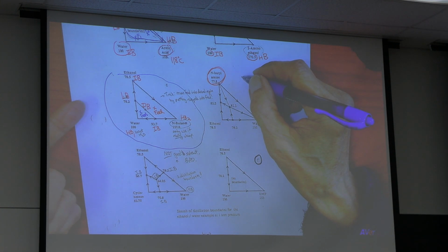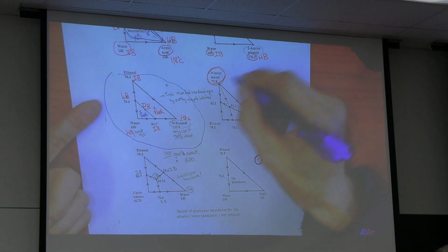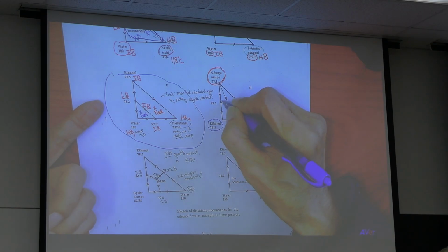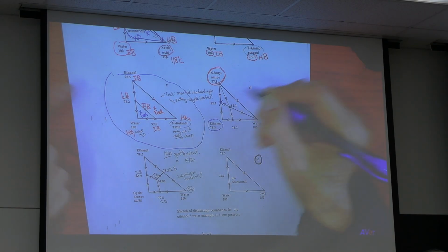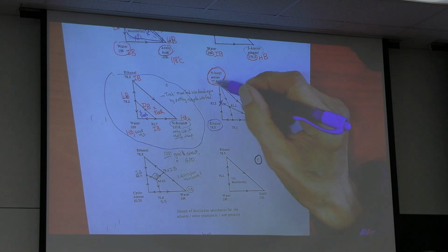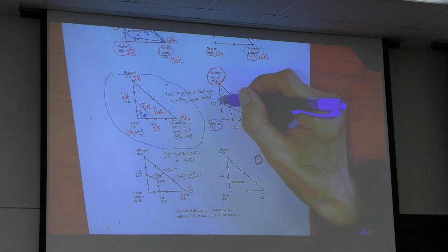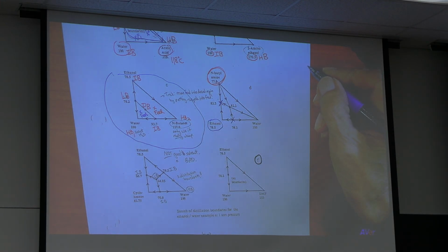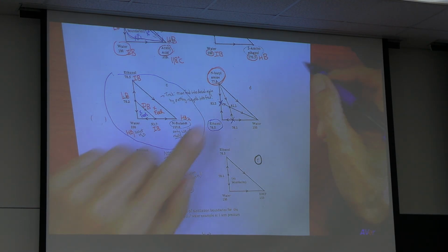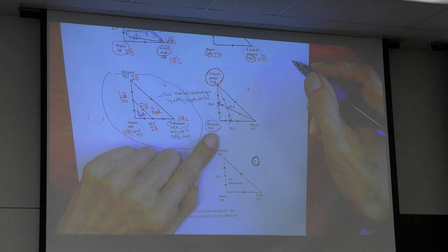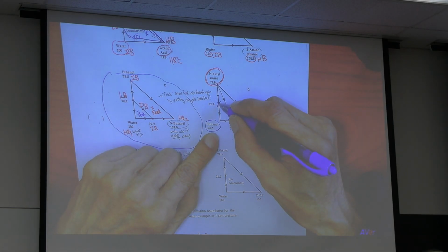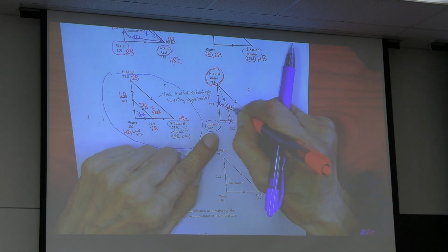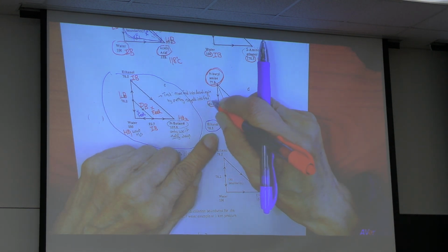You add the solvent, it also creates with ethanol a new azeotrope. You find a solvent creating a new azeotrope, troublemaker. Now, you look at this problem, not only a new binary azeotrope, you create a ternary azeotrope.